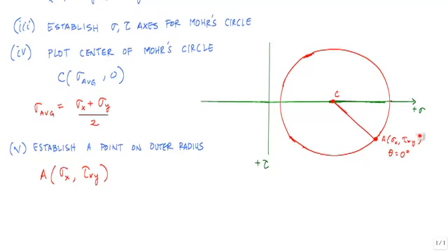And now, after you've determined Mohr's circle, or you've drawn it, it's really just a whole graphical process to calculate everything else. So one of the first things that you can always do is calculate the radius of Mohr's circle, which is just this distance, or this arm right here. And that's not hard at all when you use the right triangle. So here, bam, and bam. And if you recall, this distance is sigma x minus sigma average. And this vertical distance is tau xy. So the radius is the square root of sigma x minus sigma average squared plus tau xy squared.